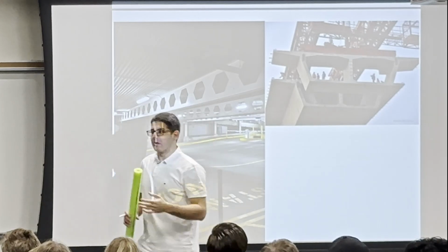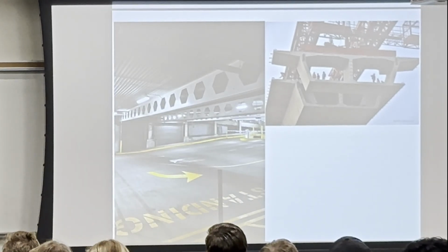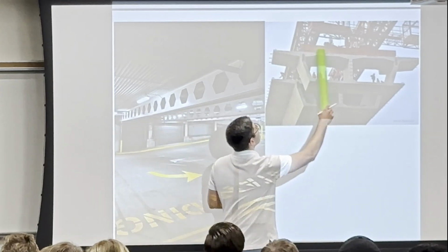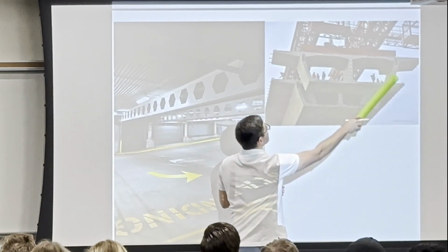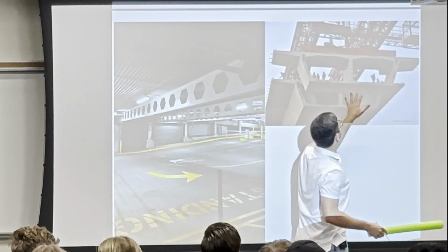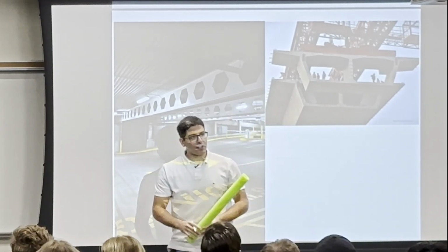If I want to manage how I distribute the material, like a resource allocation, I will put the material away from the centroid. That's why it's useless to put any material here. The only material I'll put here is just to connect the two sections together.